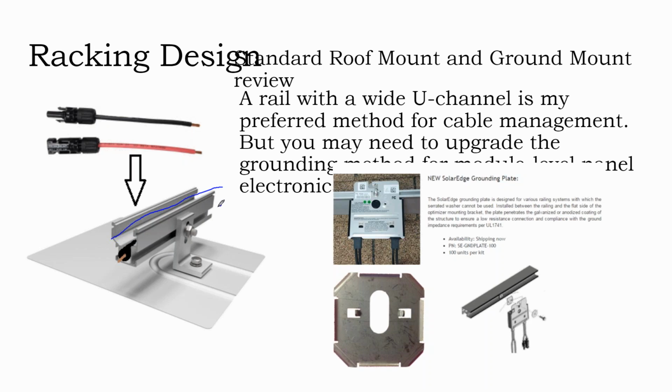Other installers will just run their cables outside of conduit or outside of a raceway, although technically this isn't a raceway, but at any rate, they'll use tie wraps or cable clips to strap the wires alongside the rail.